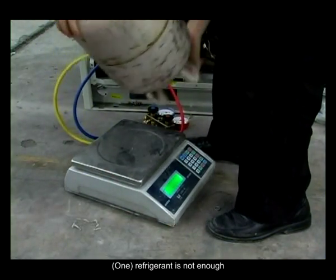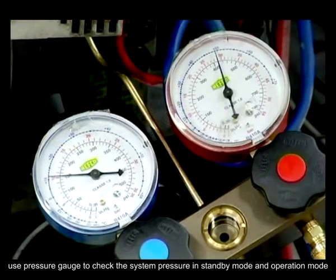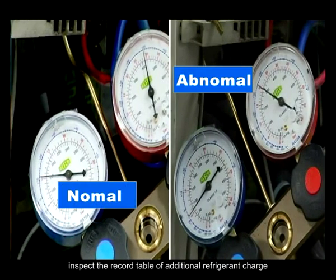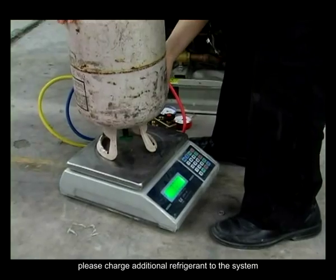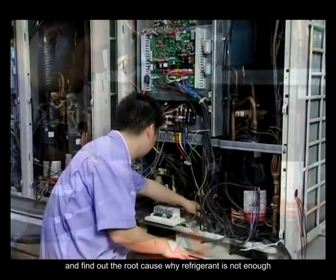1. Refrigerant is not enough. Use a pressure gauge to check the system pressure in standby mode and operation mode. Compare with the system pressure of other normal systems nearby. Inspect the record table of additional refrigerant charge. Then judge if the additional refrigerant is too little or the system has leakage. If the system does not have enough refrigerant, please charge additional refrigerant into the system and find out the root cause of why the refrigerant is not enough.